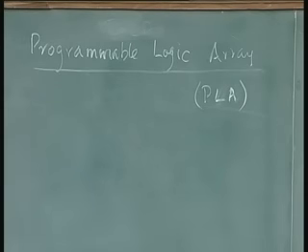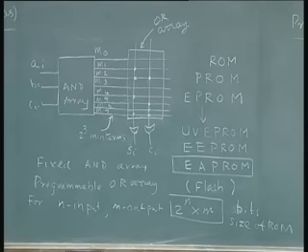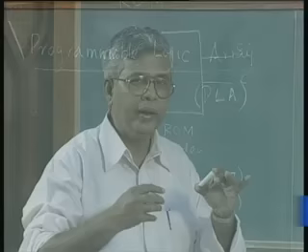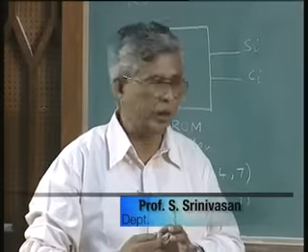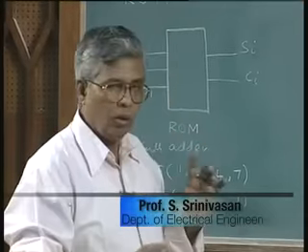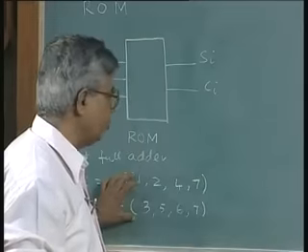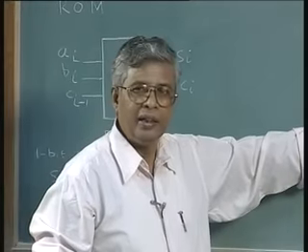I said number of minterms are generated, many of them are not used, especially when the inputs are large. So can we now generate only such of those terms which will be used, or can we only generate a few terms, product terms, which will be used in my output OR gates? In this case, we did not have to do any simplification. The truth table directly implemented in hardware form.